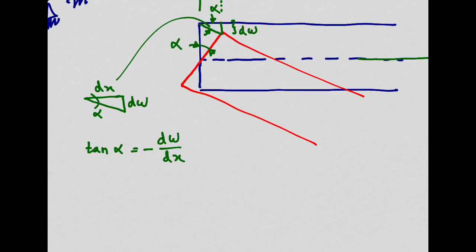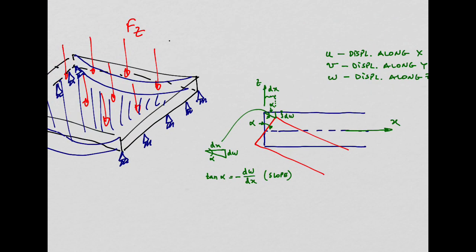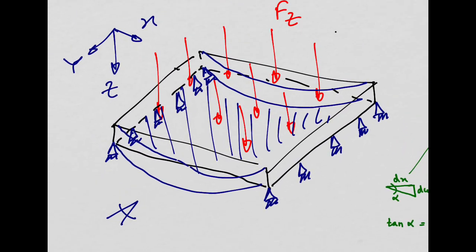So I can leave it here. So this is the slope, because it's something we are going to use a lot to impose boundary conditions in plates. So slope is a kind of a rotation. Imagine you are in this plate configuration with this support in this edge, right? So the plate is going to be allowed to rotate about this point, isn't it? So about this point here in the edge, the plate is about to rotate. So you mean the slope here is different from 0, isn't it? There is a slope there.